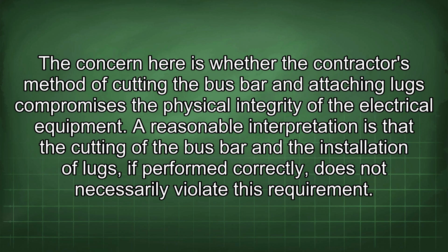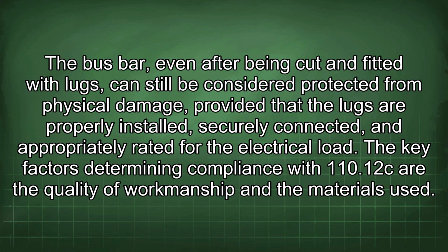A reasonable interpretation is that the cutting of the bus bar and the installation of lugs, if performed correctly, does not necessarily violate this requirement. The bus bar, even after being cut and fitted with lugs, can still be considered protected from physical damage, provided that the lugs are properly installed, securely connected, and appropriately rated for the electrical load.